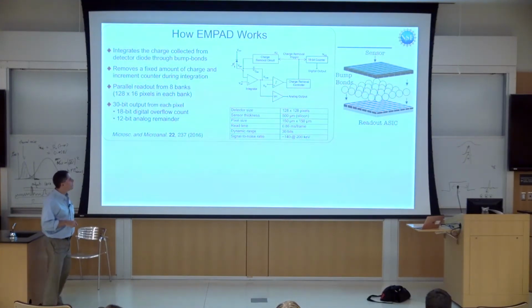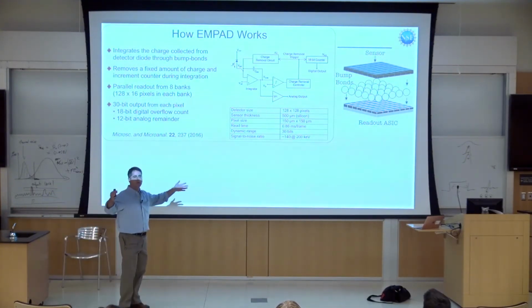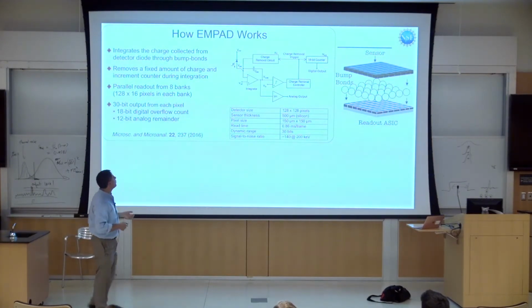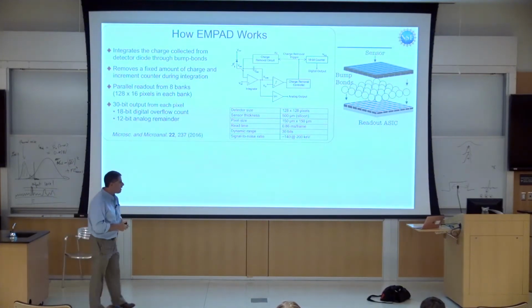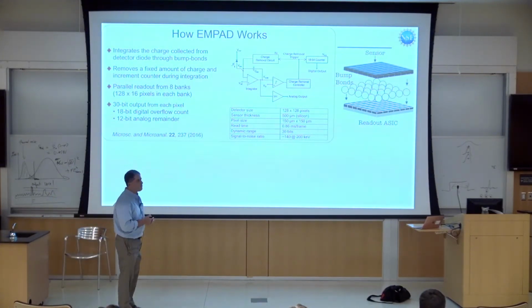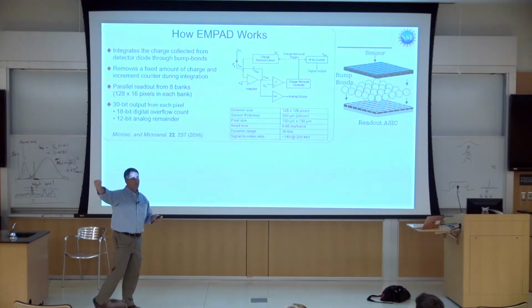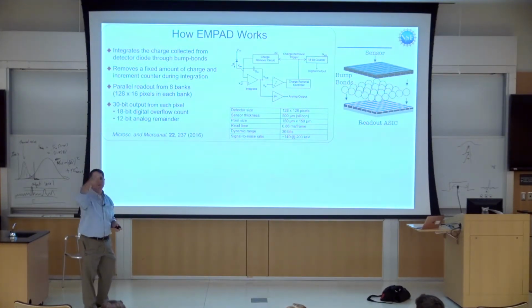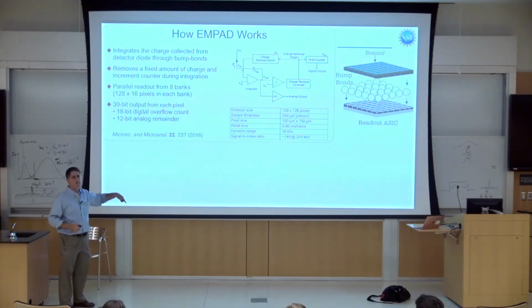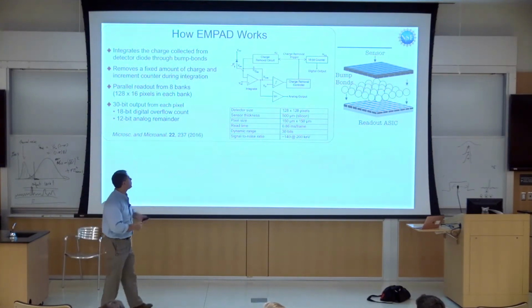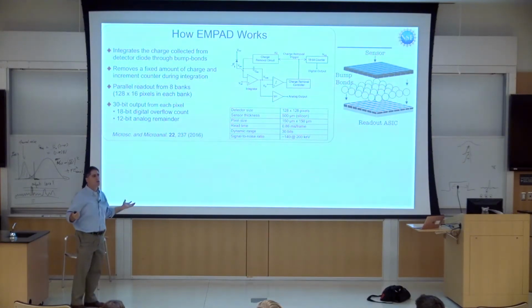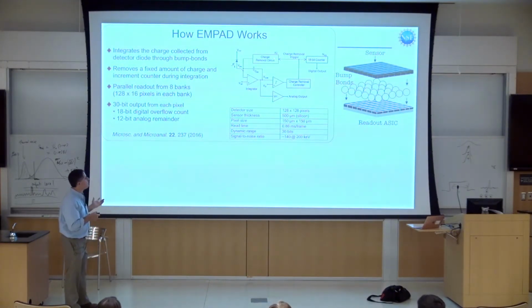What he does is he dumps charge into a big bucket. So we just simply collect the charge into a big capacitor and think of it as a giant bucket. And then he comes in with a scoop and scoops out 20 electrons at a time. As long as he scoops out the electrons faster than they pour into the bucket, it'll never saturate. So all we have to do is make sure that we have a big enough scoop to handle the charge coming in. And that's just a design choice. It's basically how big do you want your capacitor to be.